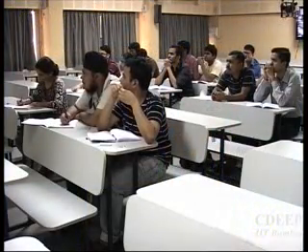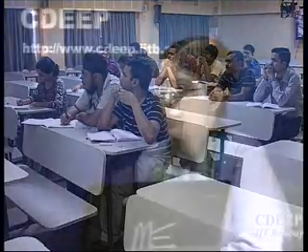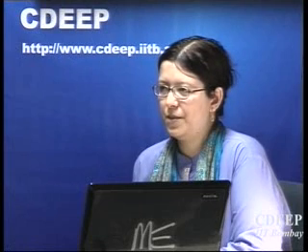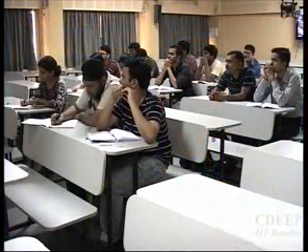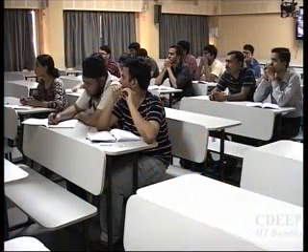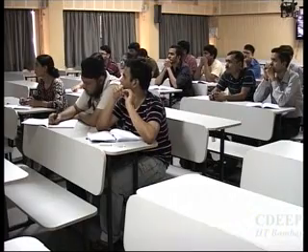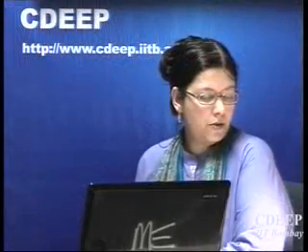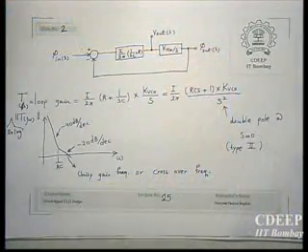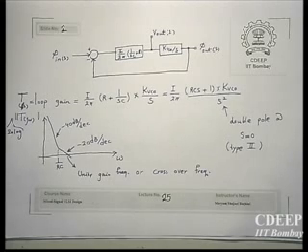And I'm saying that the output of the phase comparison, the phase difference, is 0. Therefore, you don't have any signal in there. Yeah, that is captured in this equation, in the sense that it says that though you have an input, your output is 0. It means that at least your error is 0. And therefore, when you have 0, nothing comes to the input of the VCO.